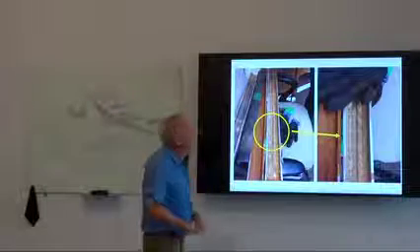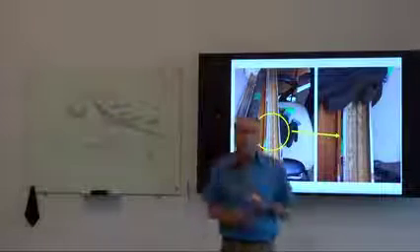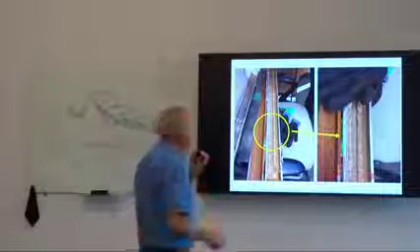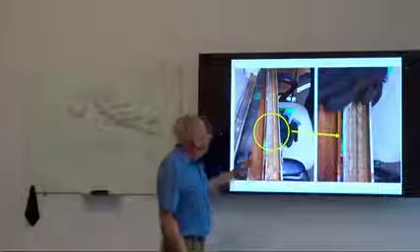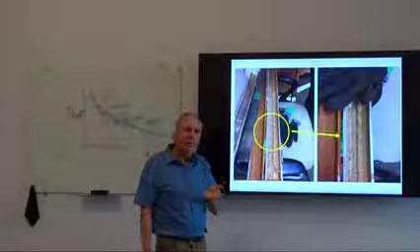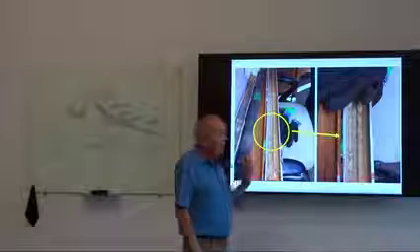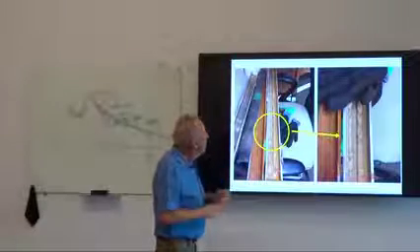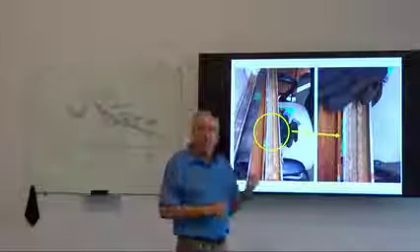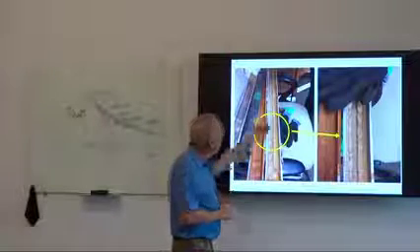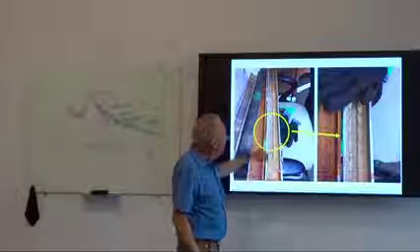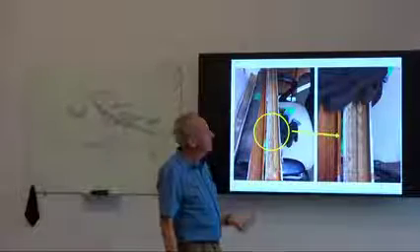And here's an example of a high GLR well from the Marcellus Shale some years ago with a customer that we were working with, and they took a section of pipe in the curve at about 45-degree inclination that was flowing above critical, according to Coleman or Turner, and yet they were having some scale issues. So when they pulled pipe, they sectioned the pipe and lifted the top half from the bottom half, and we could see these two beads of scale.